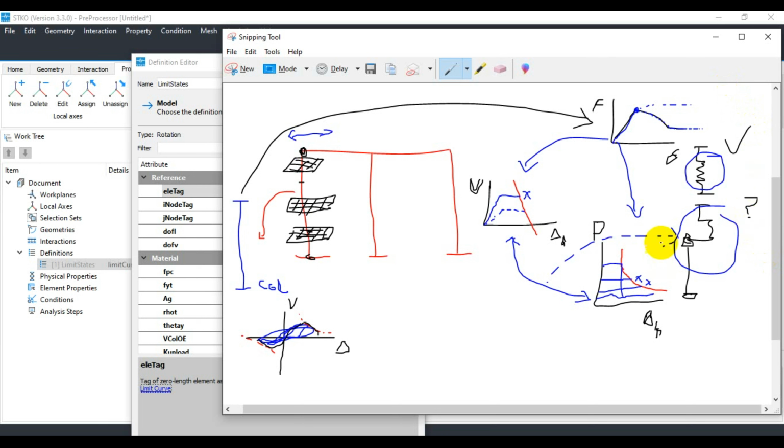by using it with SAFE or ETABS or other software. So at this point in OpenSees, it's possible to capture both the point where the failure is initiated and the response of the column to shear and axial load failure during analysis of the structure. Such a model enables the analysis of structural systems with multiple columns vulnerable to shear and axial failure as the structural system approaches the collapse limit states here.